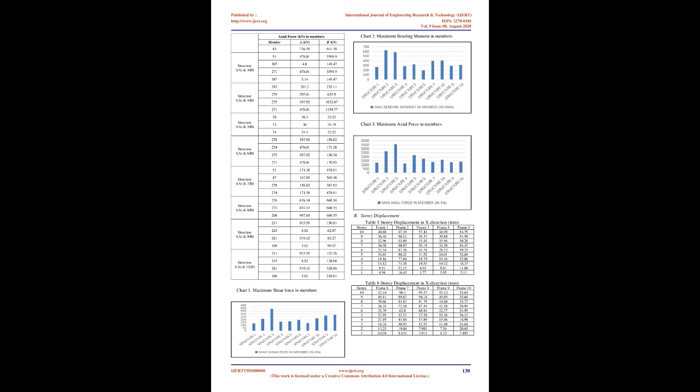Frame 9. In this frame the geometry of the building is changed by changing the height of the building in 3 bays, hence introducing irregularity in the building. Frame 10. In this frame, along with geometric irregularity, the intermediate columns are removed. Irregularity is introduced by doing so. All the frames arranged in the above said manner are shown in the figure below. Figure 2. Frames 3D view.